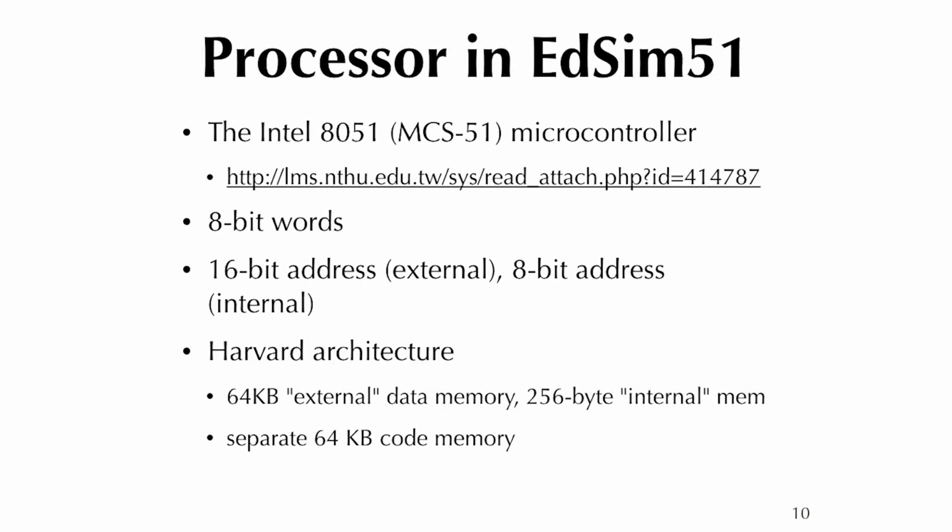So this is an 8-bit architecture. What that means is its registers are 8 bits, and it works with 8-bit units. The only thing that's 16-bit would be its external memory space. It actually has an external program memory space and external data, but EdSim51 does not support the external data, so you only have internal data. So it has these different address spaces. Internal data is something I call iData. It's only the 128 bytes that you see on the screen.